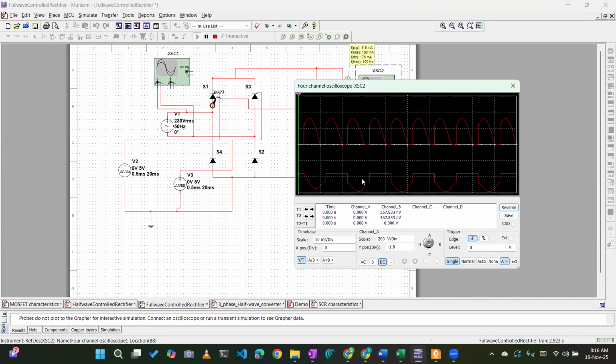The cool thing is the conduction angle is for the SCR. We are seeing S1, na? S1 current is conducting for 10 milliseconds. You see here to here. This is around 10 milliseconds. That is half cycle. But SCR output voltage comes only for pi minus alpha, that is the conduction angle, which is 7.5 milliseconds.